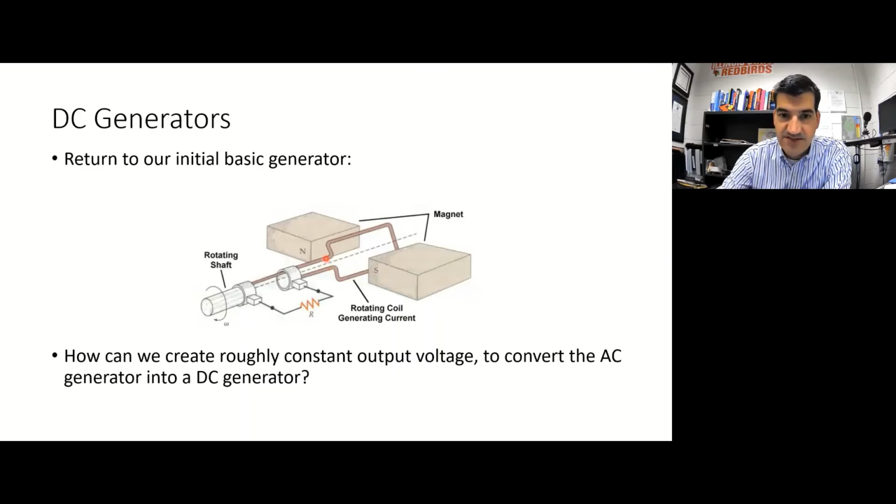So this side of the armature goes through this slip ring, but doesn't touch it, and is attached to this slip ring. And this slip ring is rotating around with the armature. And then this brush, which is usually made out of carbon, like a briquette type, looks like a charcoal briquette. That's usually what brushes actually look like in the real world.